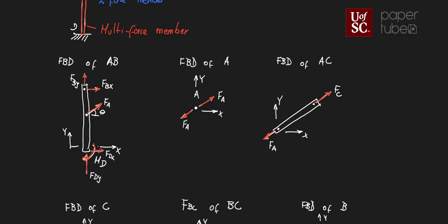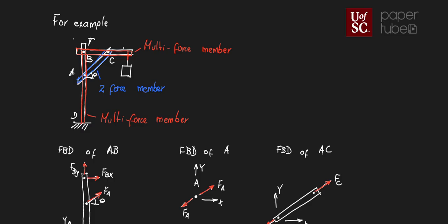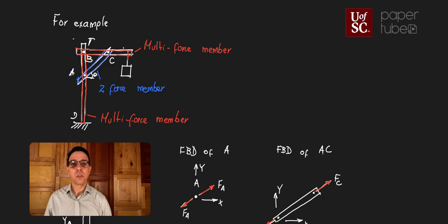Now, the other free body diagram that we can use is the free body diagram of the whole structure. So I can actually do one of the whole system and also find those reaction forces and start in that location. So in a nutshell, the key idea of this analysis of frames and machines is to be able to break down the system into other free body diagrams, and I start looking at the number of unknowns that are available in each of those free body diagrams. And then you can start piecing the information together to be able to solve for the unknowns.